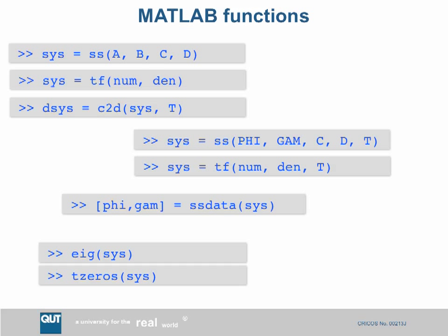Now remember when we designed phi and gamma, to get those we had to choose a sample interval. Yeah? So we've already chosen the sample interval for our system before we've gone on to designing the state feedback controller. It might be that you find that you just can't get a decent control. You then go back and say, well, okay, maybe I should sample a bit more quickly. I'll double the sample rate. Redigitize the system, get a new phi and gamma, and then play the state feedback control game all over again.